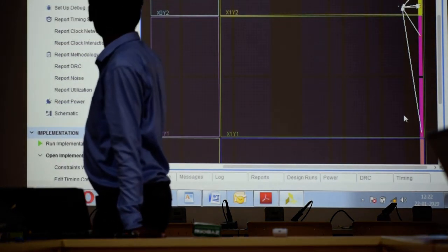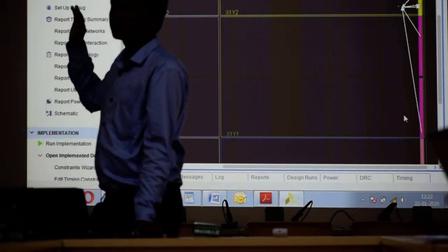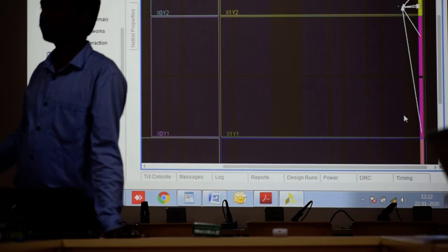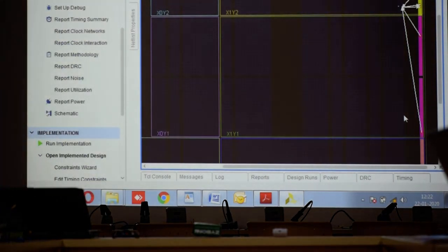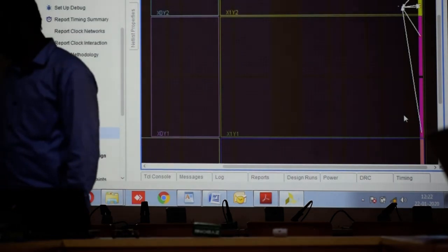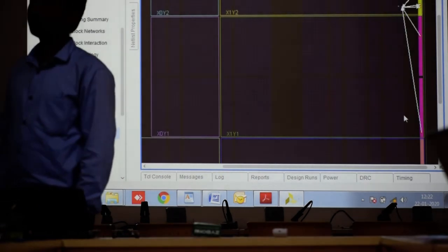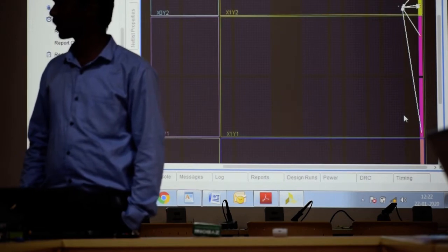It took one LUT which is near to the IO pins, and it is placed in the very corner, right? So it is not wasted. See, the entire banks are LUTs, but it took the nearby LUT, so it is not going to waste the resources. It has plenty of resources. Some 40,000 LUTs are there, but it used only one LUT, which is very near the IO banks.